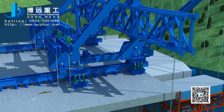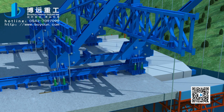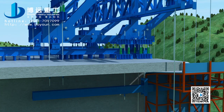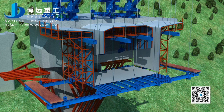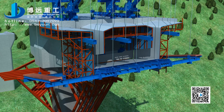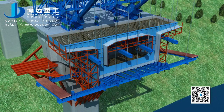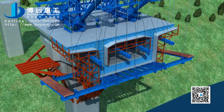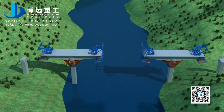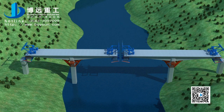Reinstall bearing hanger rod. Use bearing plate to anchor internal and external nose girder and move nose girder's rolling hanger frame to specified location to anchor. Adjust bottom support system and overall framework elevation. And begin to cast the next section concrete. Repeat in a cycle like this to complete the construction of remaining cantilever section.